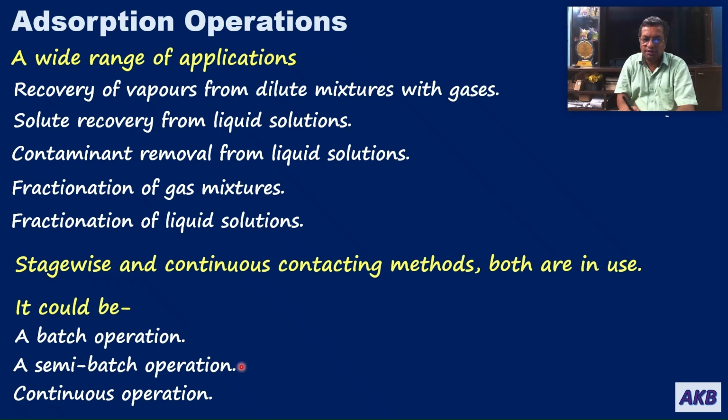As compared to other separation methods like distillation and liquid-liquid extraction, it is possible to carry out adsorption in a semi-batch manner. The adsorbent phase can be kept confined to a fixed bed, whereas the fluid phase can be passed continuously through that fixed bed. In this way, the operation can be carried out in a semi-batch manner. So in one way, adsorption is a versatile separation operation.